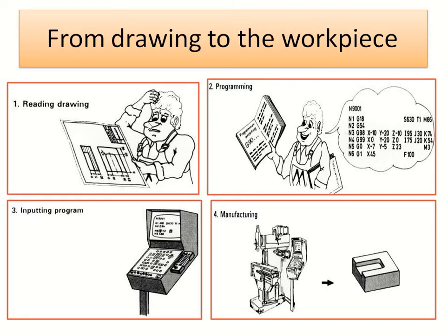So these are the basic steps we follow to manufacture any product, with the first being reading the drawing, which has the dimensions and tolerances provided. We generate the program as per the machine type, using G code and M code, and feed that program to the controller and through the controller to the machine.